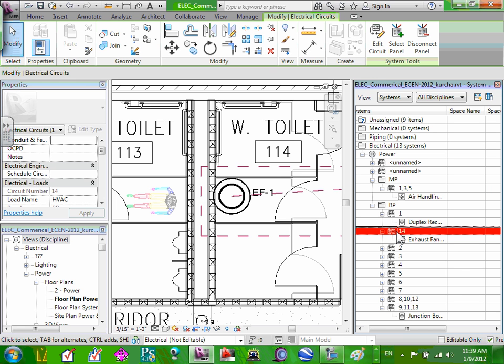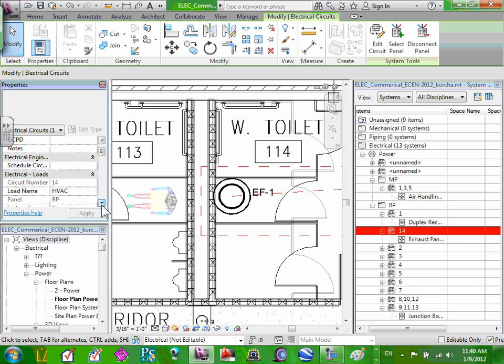This is from page 11, electrical service, page 11 circled, or 16,000-6. Okay, if you guys go there, the load name right now says HVAC equipment. What do we want to name the load when you click on the circuit? I'm going to call it exhaust fan -1. So when I see it in the schedule, it will be shown as an exhaust fan.